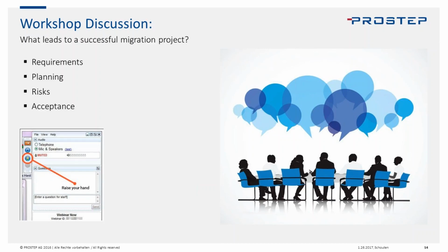I'm also a big believer in lightweights, so having an enterprise strategy to adopt maybe JT or 3D XML or another type of design space lightweight that could be easily transported between those systems would give you multi-CAD authoring capability. If that design is owned in one, they generate the lightweight and send it over to the other so it can be consumed.